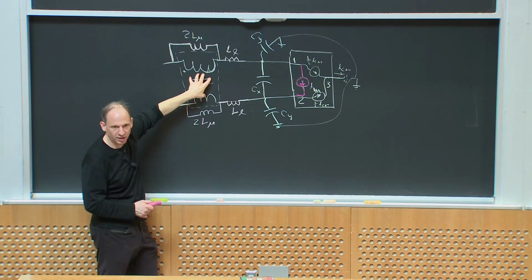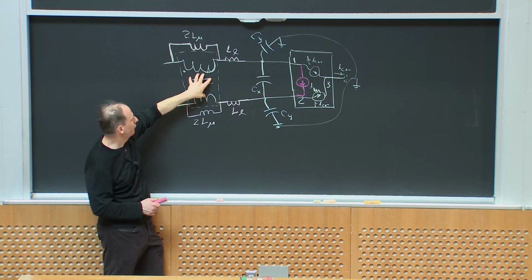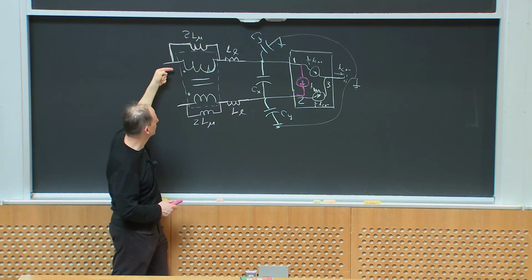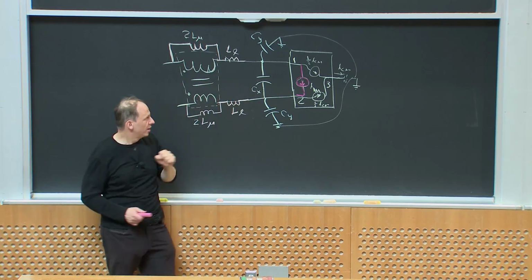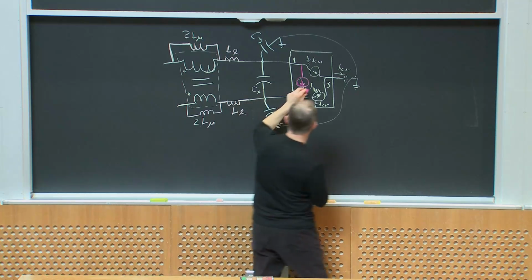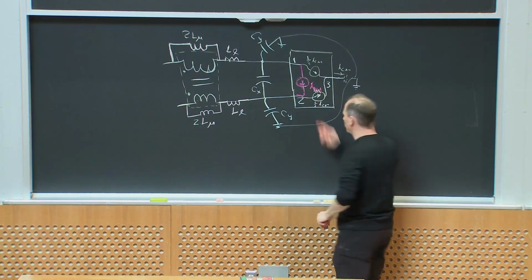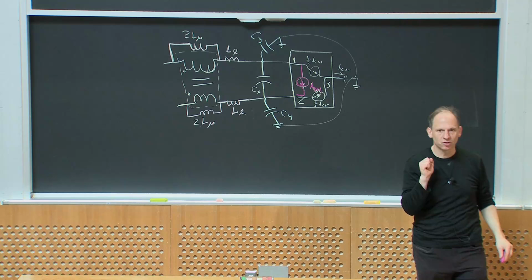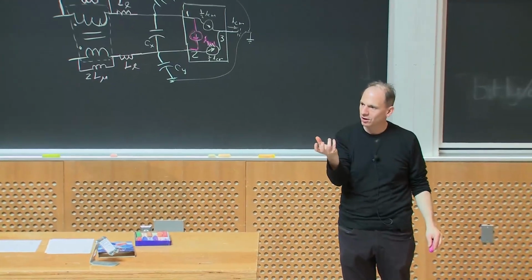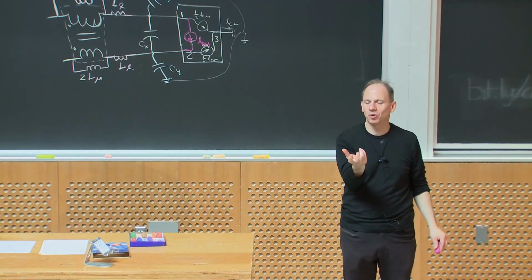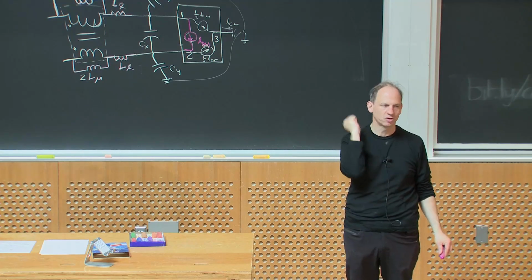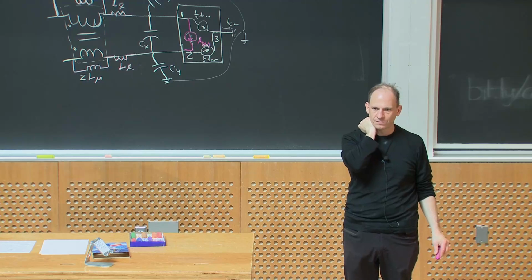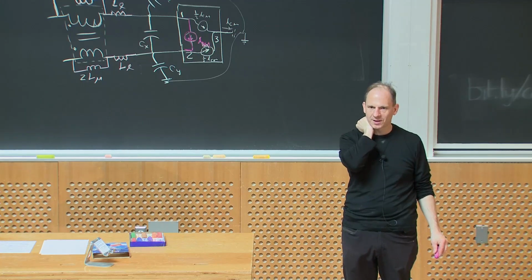This common mode choke, the ideal one, is a perfect short for differential mode currents. So the differential mode currents don't go through the magnetizing inductance, they just go through the ideal portion of the transformer. And so you don't magnetize the core. And so even if you have high differential mode currents, because this is what you're delivering power to the device through, they don't magnetize the core. And so you don't need a big common mode choke to get a high effective common mode inductance. Okay, because it doesn't store any energy. At least it doesn't store any differential mode energy. Any questions about that?